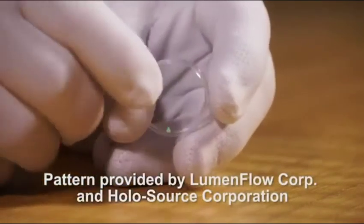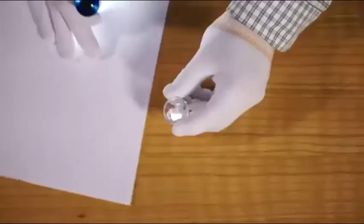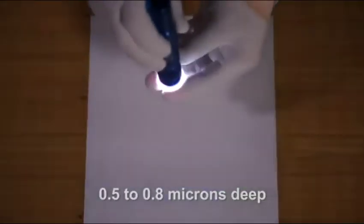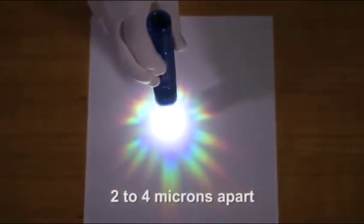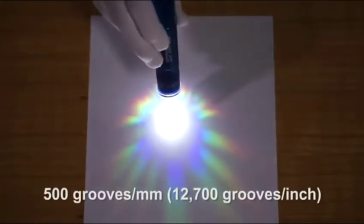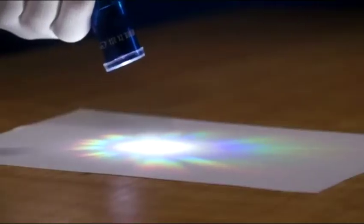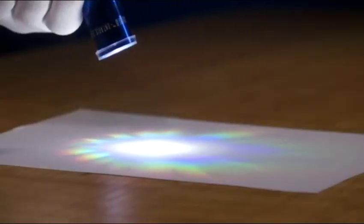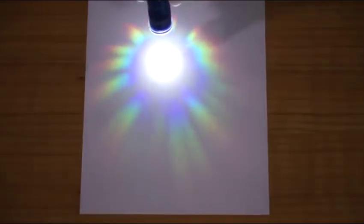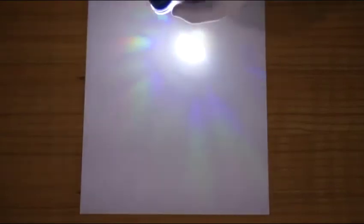The molded pattern is a set of flakes or chips that have grooves across them. These grooves are just 0.5 to 0.8 microns deep and are 2 to 4 microns apart. At a 2 micron spacing, that would be approximately 500 grooves per millimeter. This fine pattern acts as a diffraction grating. It diffracts or splits the light into a series of rainbow spikes around the center beam when placed over the collimator lens on the flashlight.